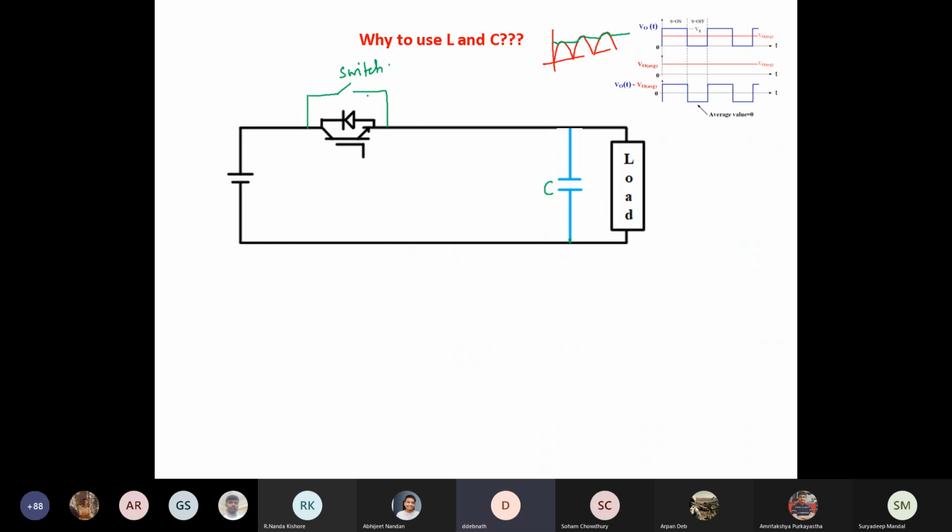Even after this, we will get a bit of the green type waveform that you have shown. So we might need to use a regulator as well. But otherwise, I feel this will filter out the major pulsating DC component. Okay, so you mean instead of getting this kind of flat DC, I may be getting something like this, is it? Yes. This is the only problem that you're thinking, right?